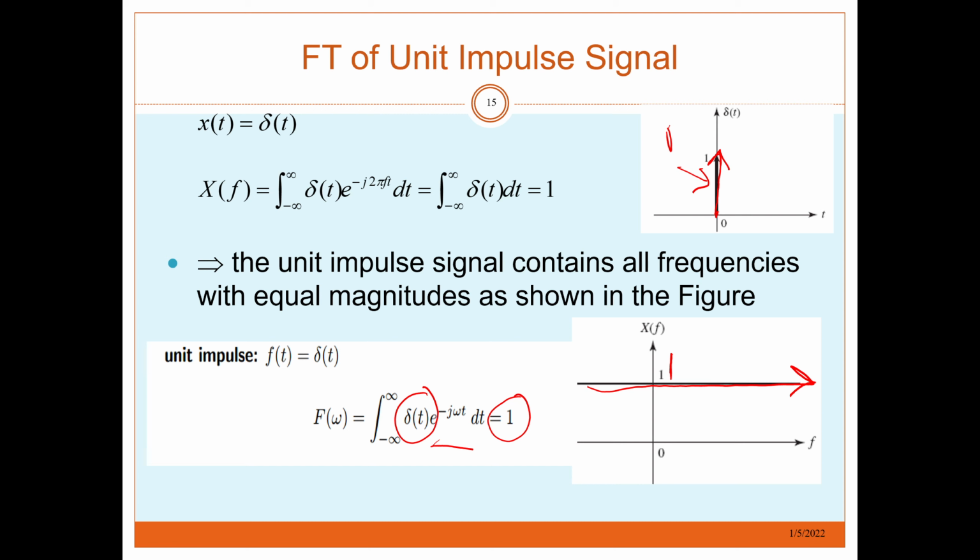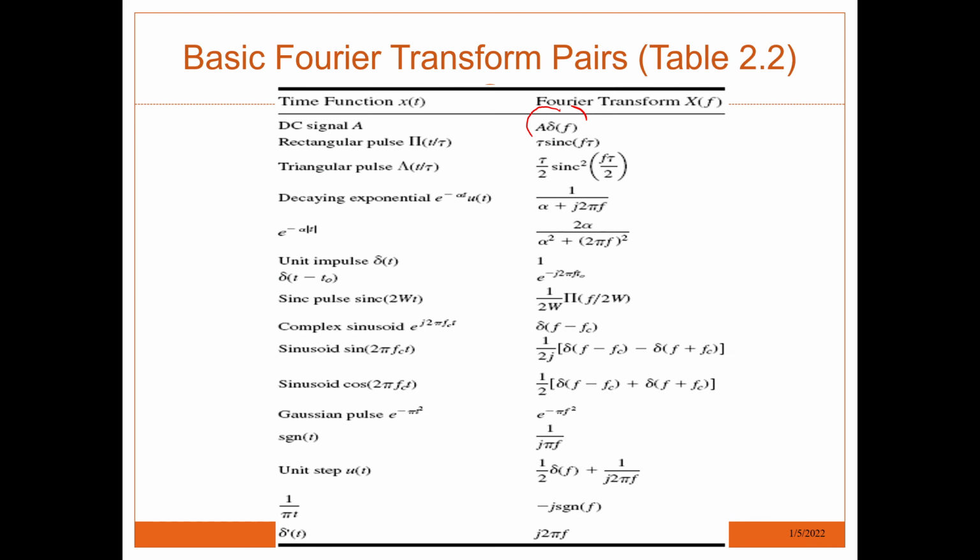A delta in the time domain is a DC signal. So this is the relationship. And we also saw just now that a rectangular in the time domain is a sinc function. It can also be vice versa. If the time domain is a sinc function, the frequency domain is a rectangular. All of it is vice versa.